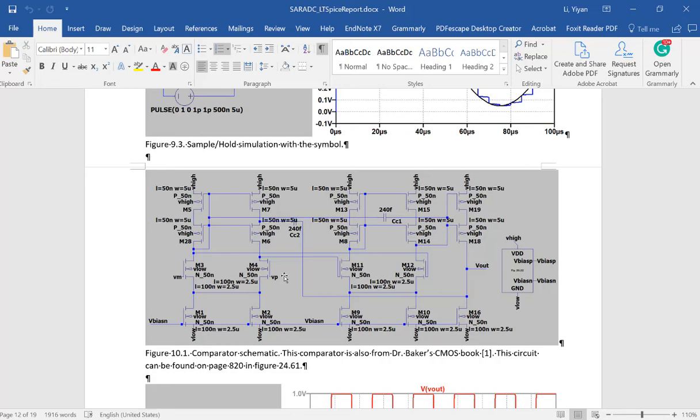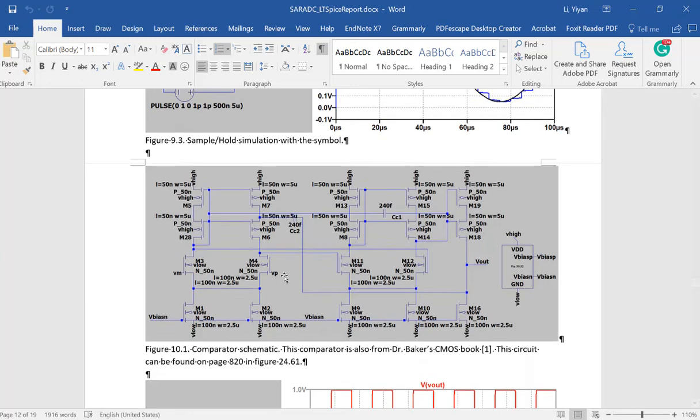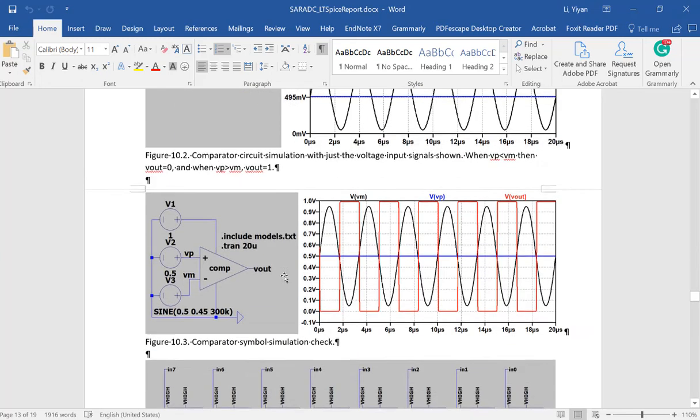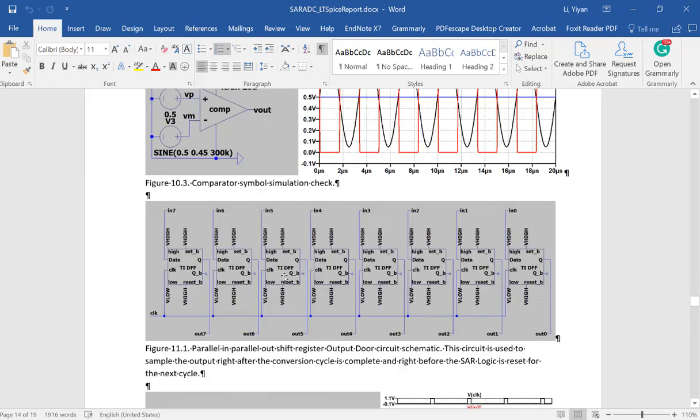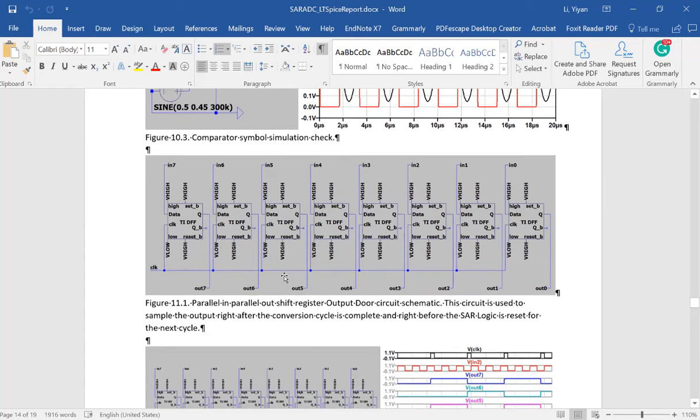It's analog swing, right? The analog input is swinging around one base point, and you have power supply, VDD, and ground. And if you have a design like this one, it's not rail-to-rail, which means whenever the swing is getting closer to the top, like 5 volts power, it's going to be cut on the top. So you do want a rail-to-rail swing. So there is another design we can consider, right? A comparator is actually an op-amp, but nothing else.